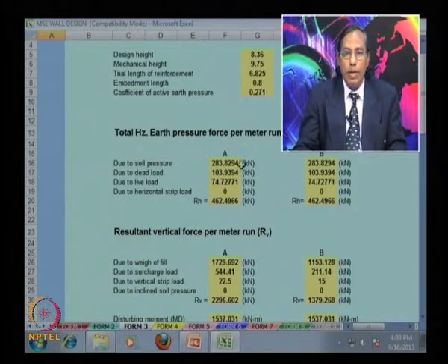This design has been made as per the British Standards Institution 1995, and combined load B is where it is due to the overturning load. So for soil pressure, you have calculated this value for A and this value for B. Due to the dead load, you know Ka, you know the Qd value, and you also know the H value.